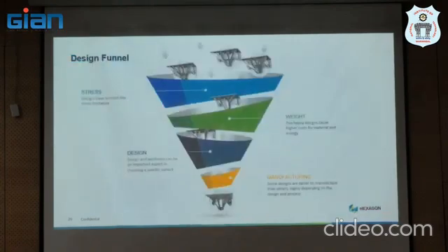So how does this complete optimization or DFAM funnel work? We have seen stress based optimization. First it will check the stress throughout the component and it will subtract or add material. Then it calculates the weight, how much weight has been optimized from my original design to the final design. Then design complexity, because as I said, we have written a lot of algorithms saying that you don't optimize less than 45 degree, reduce the wall thickness, all of this will be checked. Then the manufacturability.